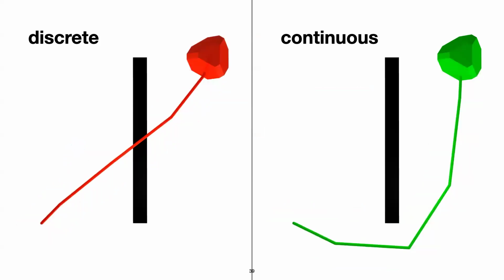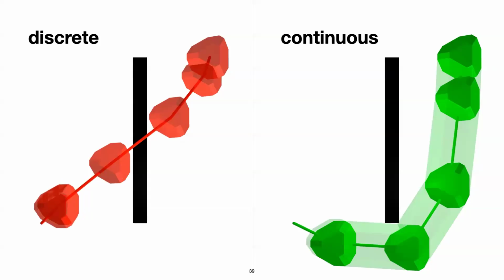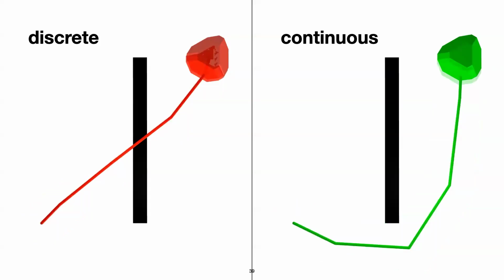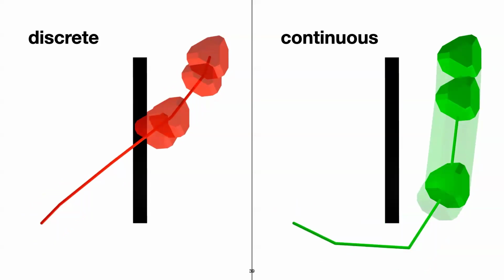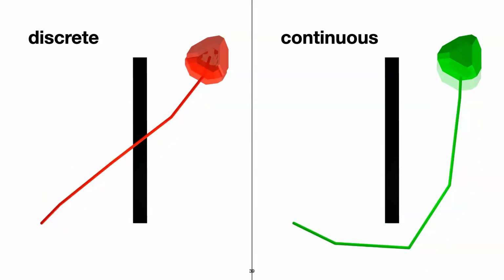So the solver can effectively just speed through the wall if it goes a little bit faster. Then on the right, we use our new formulation where we're considering both alpha and tau as we slide it on this track between the 2 time steps. And we see that basically we don't let the solver cheat. We don't let it speed through or tunnel through the walls themselves.